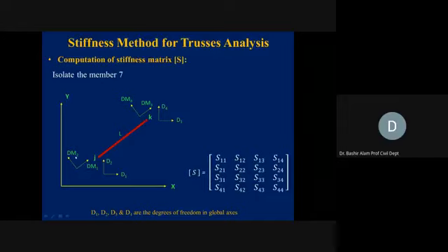So what will we do? DM2 we will restrain, DM3 and 4 we will restrain, and we will give displacement only in the DM1 direction at this joint J. And how is that possible? If we provide a roller here and start pushing it along this arrow, a unit displacement will be given. The definition of the stiffness matrix is: force required to produce unit displacement.